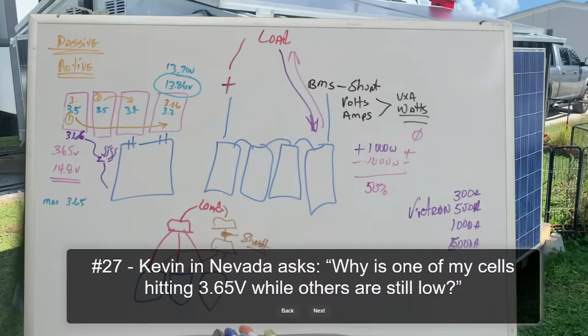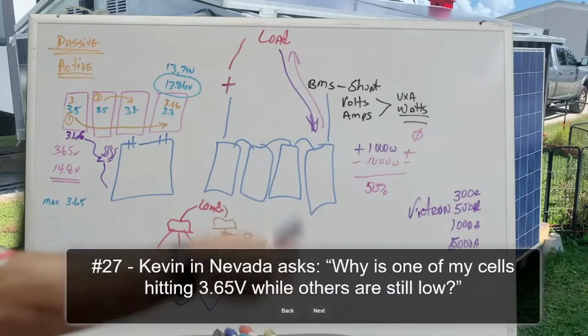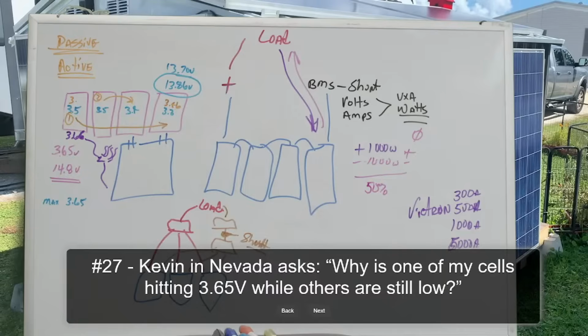So you probably could set your charge voltage down at 55.8, or 55, or even 56, instead of charging at 56.2 or 56.8 or 57 or even 58. You just lower that voltage to where it is the highest it can handle before the BMS cuts you off.